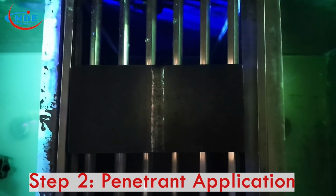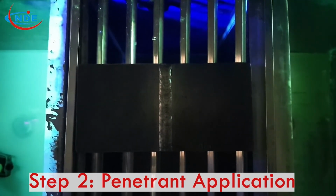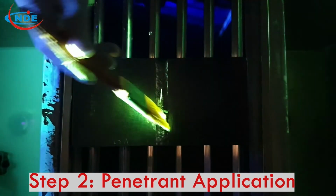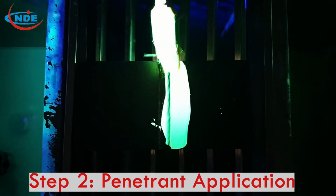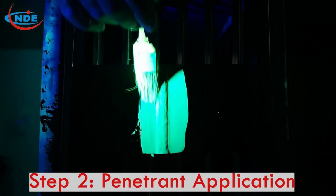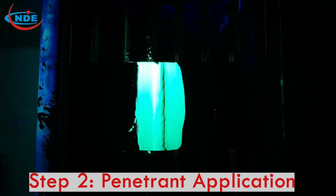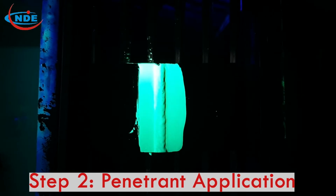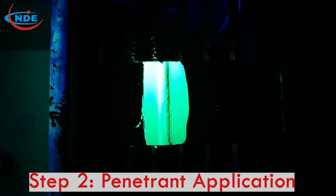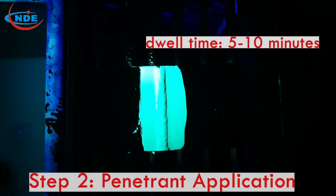Step 2. Penetrant application. We can spray or brush penetrant to apply on the surface of the testing object. Notice that during the penetration time, do not let the penetrant become dry on the surface. We can spray or brush to add more penetrant. The dwell time is about 5 to 10 minutes.